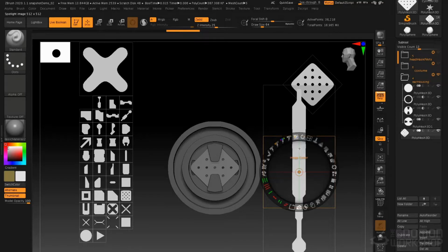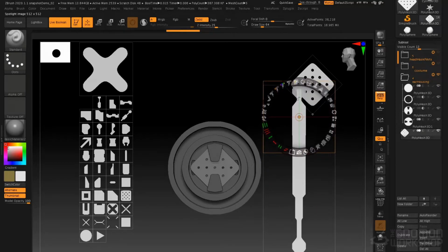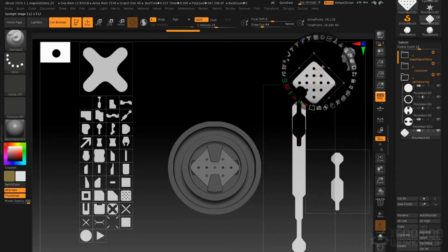Click on the y-axis and hold the Shift key to force it to go up this way. I am going to scale it down, and then I'm going to press Alt on the Union button. The Snapshot button makes geometry. This button allows me to manipulate alphas. If I Alt-click on that, it has just subtracted that shape from both alphas that were overlapping it.